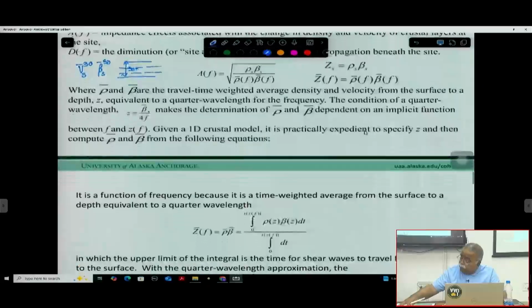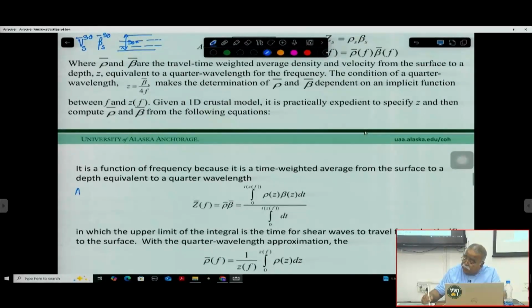The soil type can be A, B, B oblique C, C, D, C oblique D, and so on. They have different velocity values, and velocity means VS30. So VS30 has been taken as a parameter for earthquake hazard assessment, and it is included in the seismic design code.